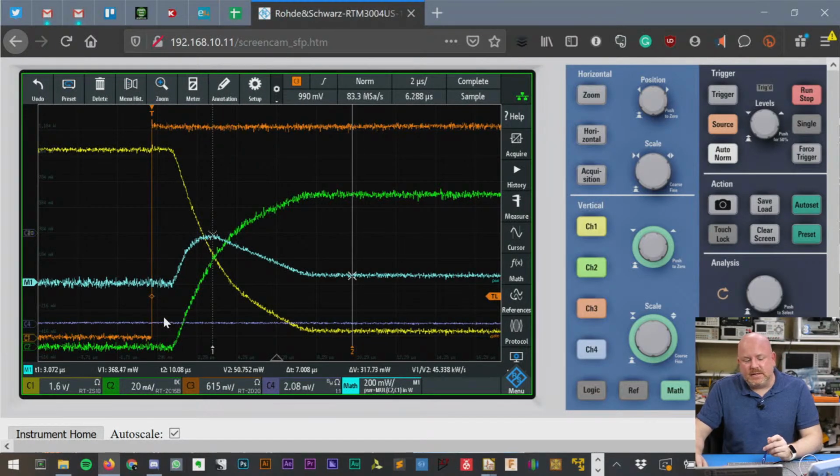What I really like about this is, and these two sets of measurements were not what I originally intended to build this board to do, but I'm glad it worked out, because with a 0 ohm resistor, we can see the Miller effect, and with a ridiculous gate resistor value, we can see the slow switching effect.